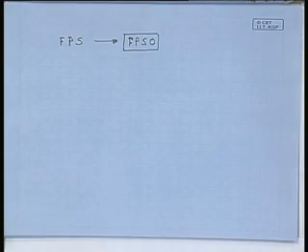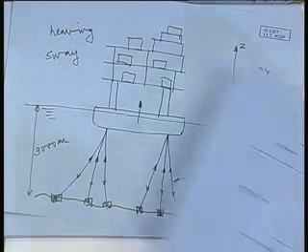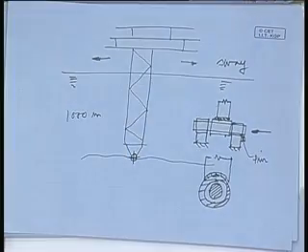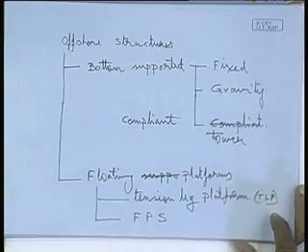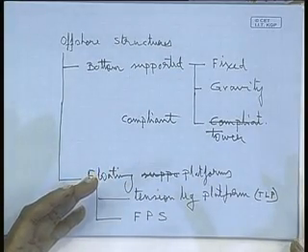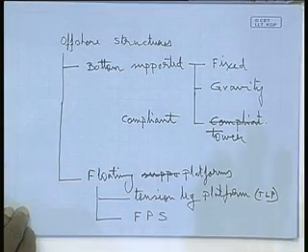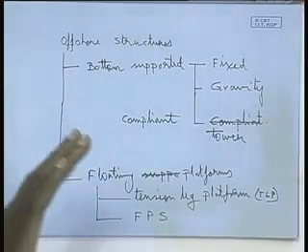In all the previous offshore platform types that we have seen, one thing you can see is that all of them are location specific. They are fixed to the location. That means, when we are talking about the fixed platforms, well, it is literally fixed. There is no way you can move it. When you talk about gravity platform, though it is not fixed, for all practical purposes it is fixed. Once you install a gravity platform in one place, when that oil gets dried up, you are not going to remove that platform from there, because it will be a huge job and totally unnecessary.